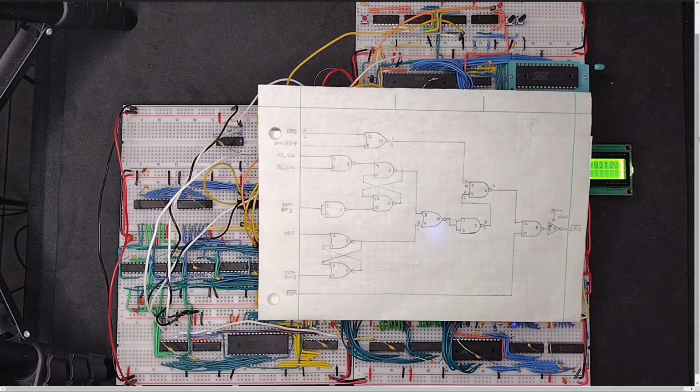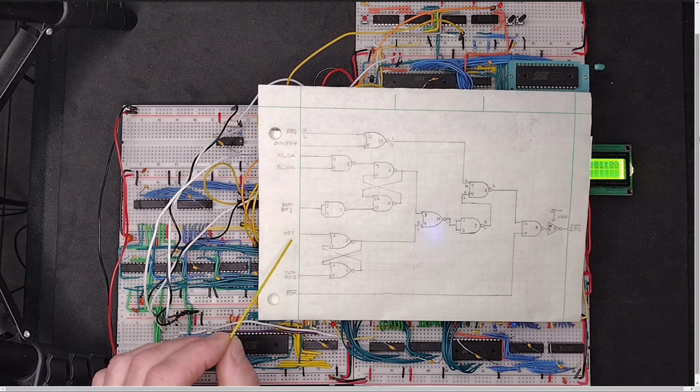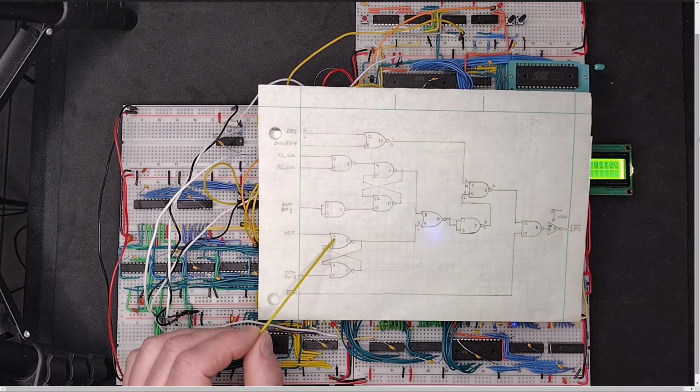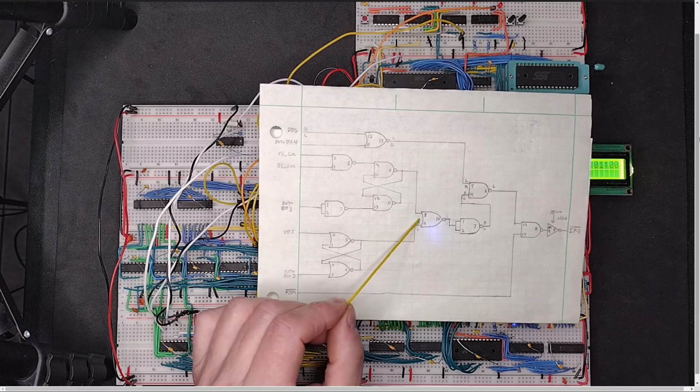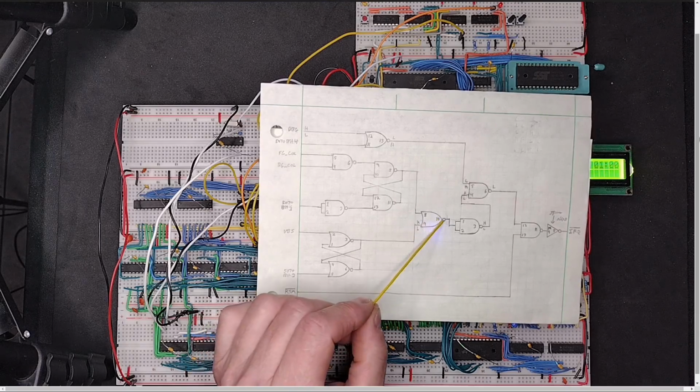And that's just a quick pulse that I set up with my video card so that the output of the video blank signal will just pulse for a very short time. I have it for 3 clock pulses, so that's 3 of the 10 megahertz pulse signals. So for 0.3 millionths of a second, this signal will be pulsed high. And that will cause this to go high. And when this goes high, then it goes to this NOR gate. This is high, so the output of the NOR gate will go low.